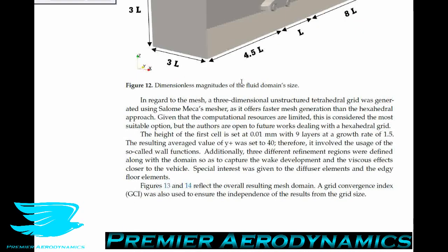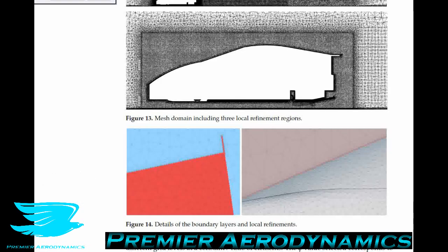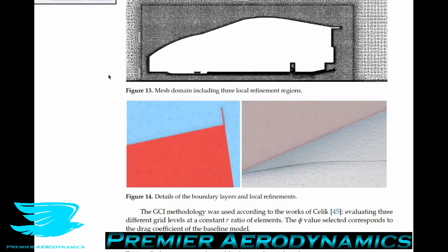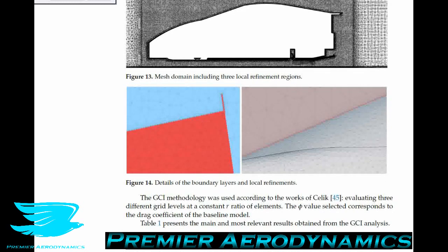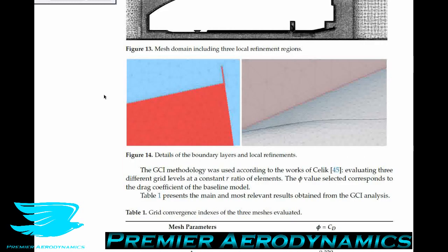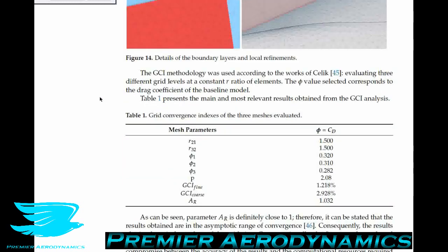It's not really a good idea to do, but if you want to, then that's, I guess, up to you. Anyway, their grid convergence study in this work is definitely better than what we've seen in the last couple of podcasts, mainly because the difference in the number of cells between each refinement is a non-negligible number. Each refinement resulted in 50% more cells in the next level upwards.